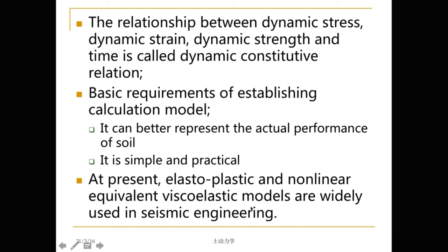Here I say the elasto-plastic model is valid not only in steady conditions, but also in dynamic conditions. Here, the nonlinear equivalent visco-elastic model I already introduced is composed of some elastic elements, viscous elements, and plastic elements, and they consist together to create a model, and this model can be described using visco-elastic model parameters.